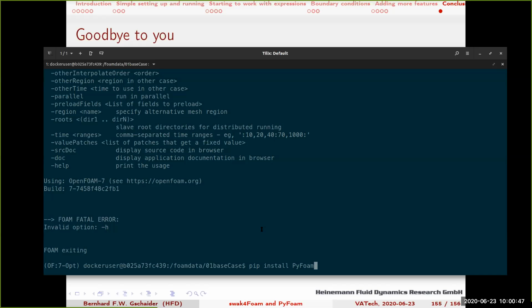So it's from Lorenzo. Do you have a clarification, Lorenzo? Are you asking, is it like higher order interpolation? Yes, higher order. If I want to obtain, for example, I have a DNS and I want to obtain the filter quantities to do an a priori LES, I can use the map field, but the interpolation is of order 0 in the sense that it takes only a spatial average. Is there a functionality to obtain better filter quantities of higher order in terms of interpolation?